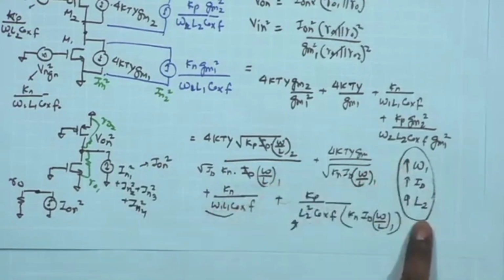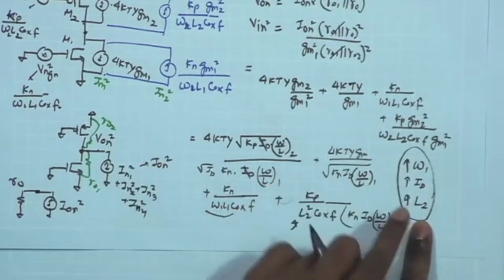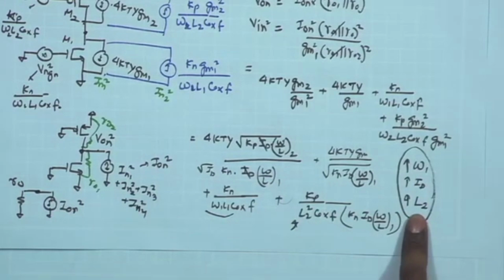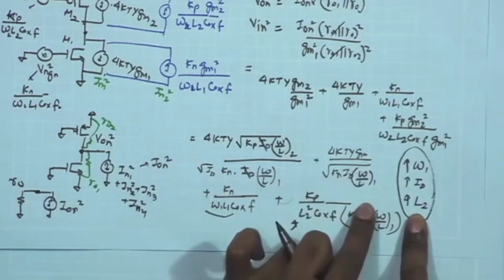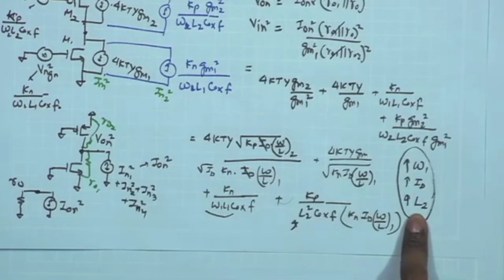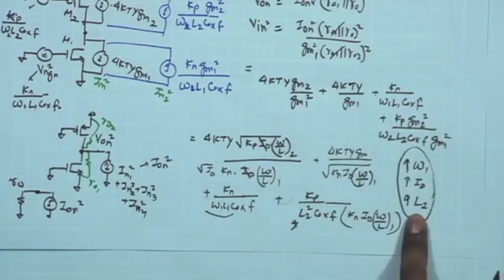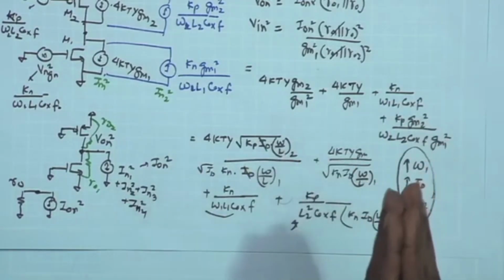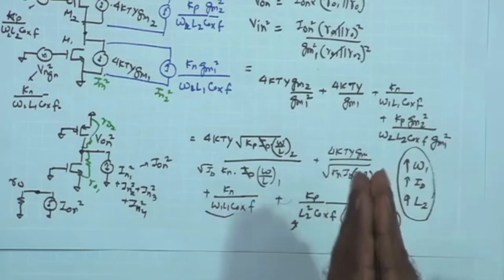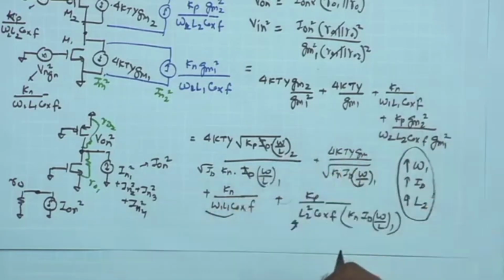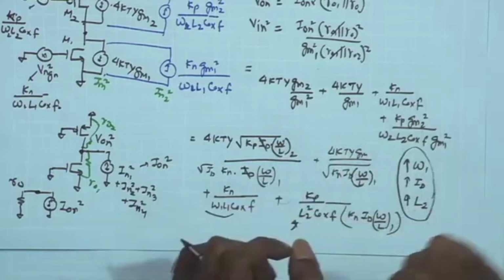Likewise, the other terms, if you go on increasing W1 or the device size L2, they are going to affect my bandwidth because they are going to increase the device parasitic capacitances and slow down my overall frequency response, and we need to cater to up to at least 100 hertz or 1 kilohertz of signal. So, being conservative, we would like to push the upper cutoff frequency slightly higher than the signal content. So, signal content is from 0.1 to 100 hertz.